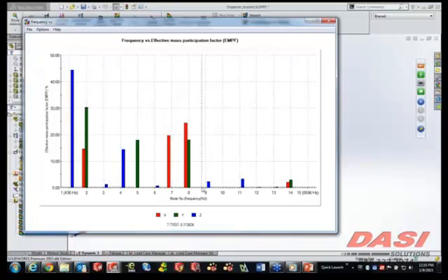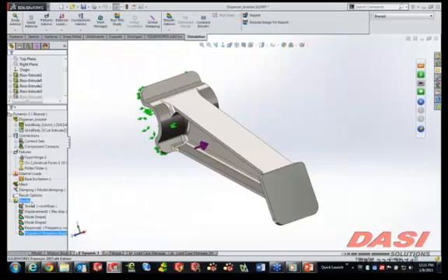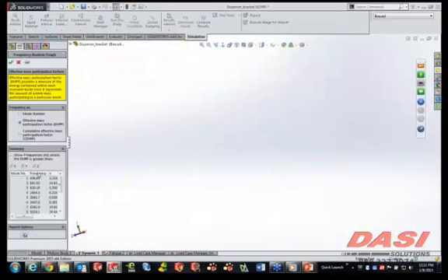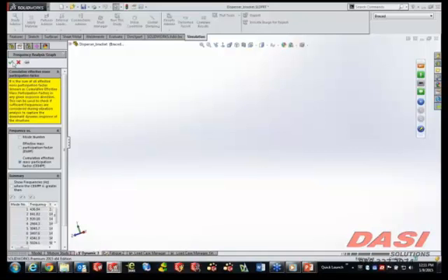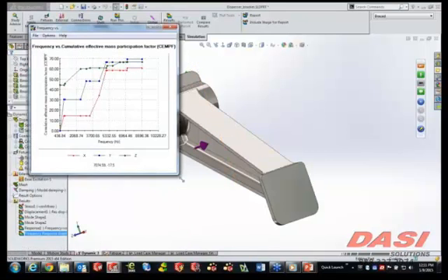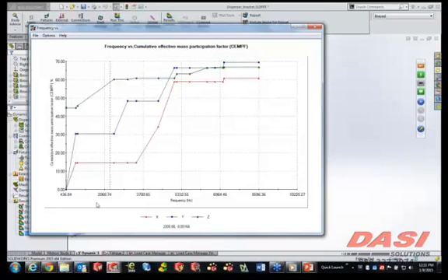But it does show up in other areas and a little bit lower loads in this particular case, the mass participation. We also have a plot similar to this, but a little bit higher order, that's called the cumulative effective mass participation. And what that's going to do is show this in a different type of a chart, but it gives you the same detail that we can glean. So here early on in our mode shapes at the frequencies, we're getting very low X and Y values, but Z is very high. And then as they start to converge at different modes, we can see that Z moves more to the middle where X and Y are going to bracket that a little bit more. But in any event, it's much more usable data to glean off of this than we had in previous types of charts.